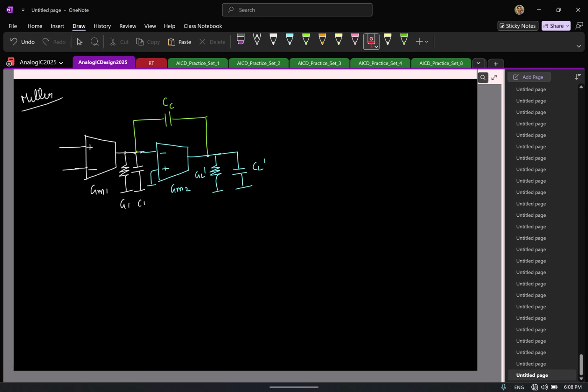Sorry? Yeah, you probably have to add one more stage and do something. But is there a systematic way to get it? In programming, what do you do in recursion? Yeah, the idea is now you have a two-stage OTA, just like in recursion, where you keep doing things recursively. You replace this by another two-stage OTA, right?